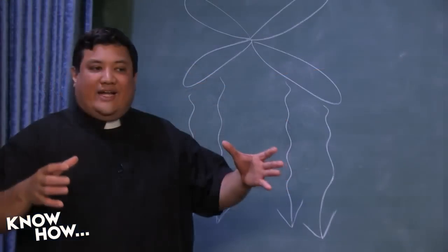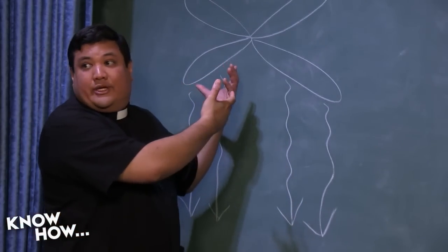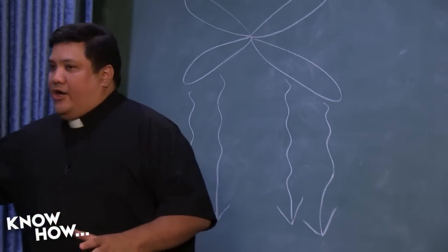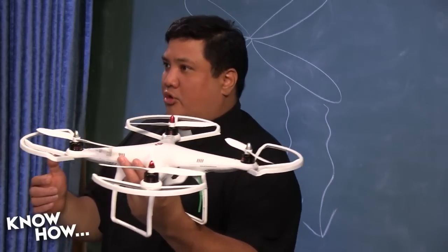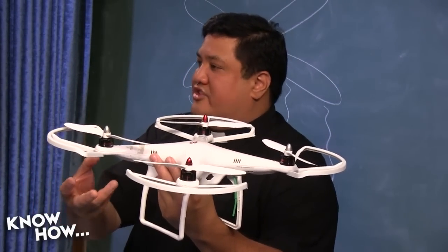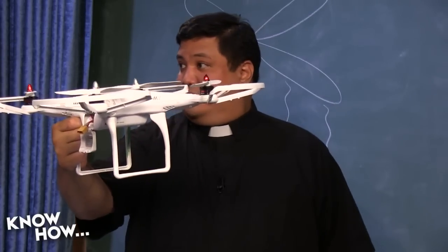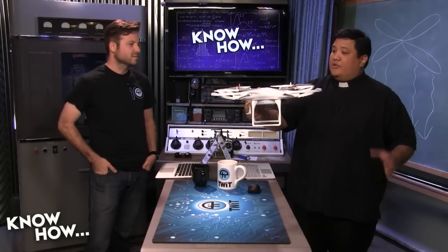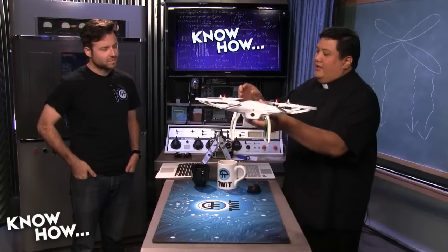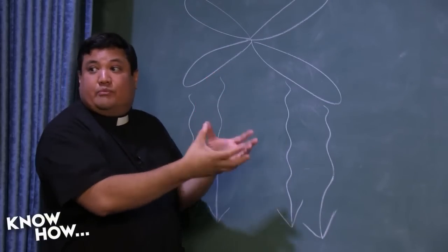Well, the problem is that dead space creates this sort of current, this eddy, where you get an updraft in the middle. Normally that doesn't matter, because if you're piloting a rotary wing craft like a helicopter, you're typically moving, and as you move, that updraft just gets left behind. The problem is, one of the things rotary craft can do is hover, or descend straight into their own prop wash, or when you have to land. As you do that, this zone actually starts to spread out. It gets bigger and bigger.